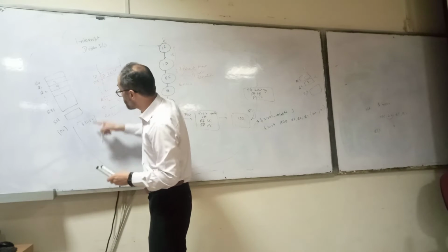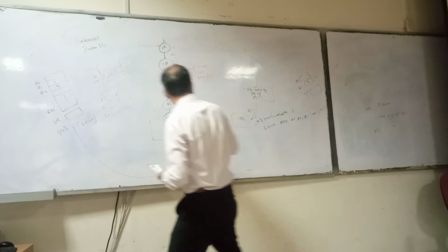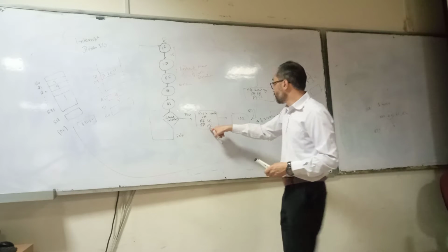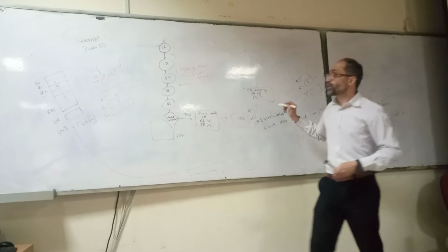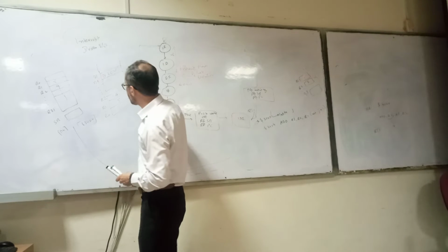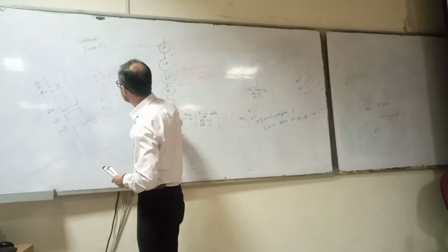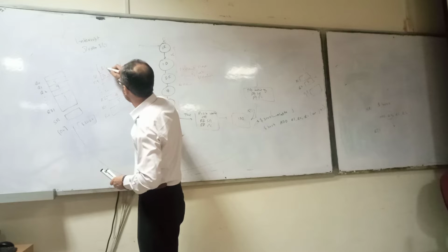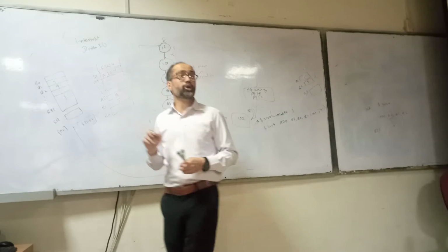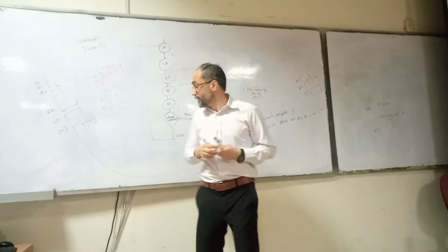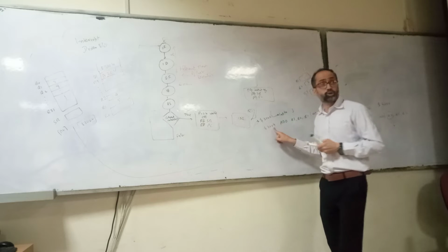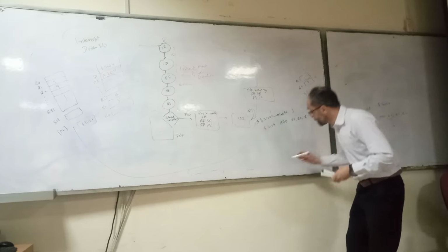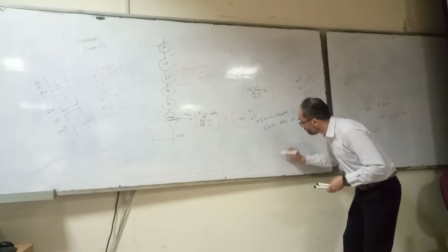And then, last of all, it also pushes the value of the program counter. The value of the program counter is pointing to the next instruction. So actually it will push the program counter on the stack. So what is the new value of the program counter? $3004.